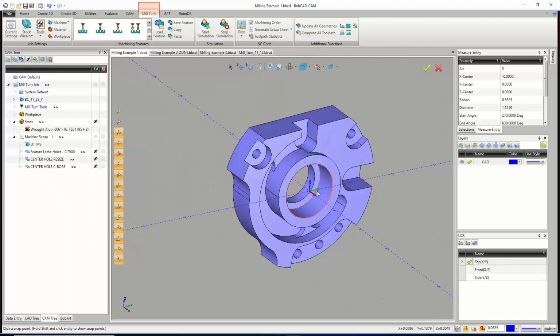So now that we have that done, the next step is going and kind of figuring out this outside floor right here. Now, I like to use an open pocket when I do that, but I don't want to try and say detect open edges because there's a lot. Like this little pocket here and these little cutouts here, those will be fine for the detect open pockets. But I want to go and get my geometry off this.